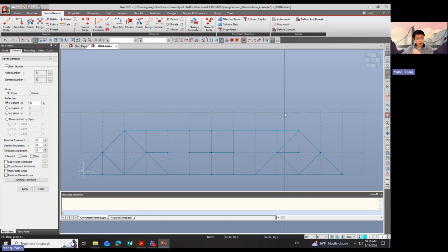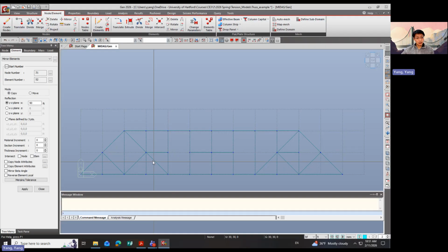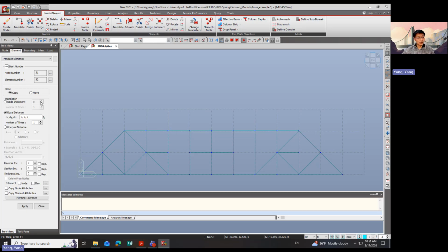Okay, and also we can make copies there. Make copies. So diagonal ones. Basically, we will have a copy for the second row here. Second row here. Make copies. So here we have translate from the x direction, and so by 2 parallels, so that's 30. So the dx should be 30.